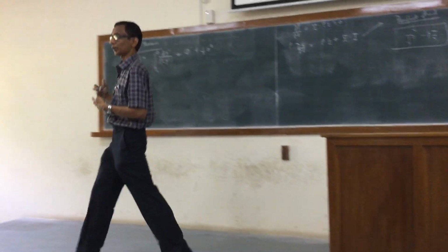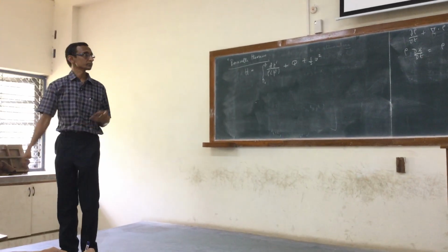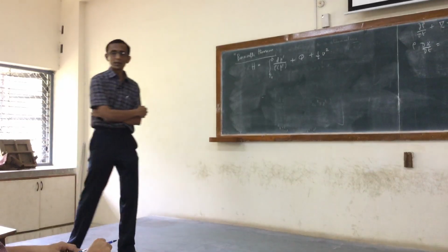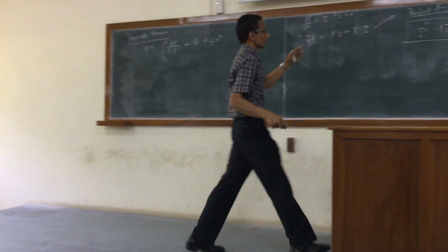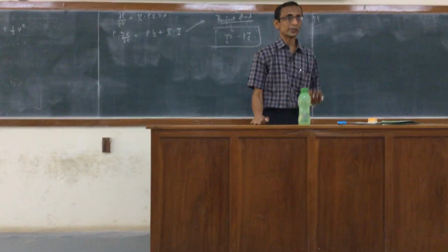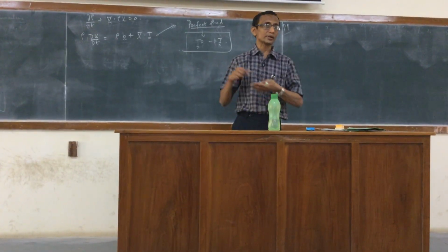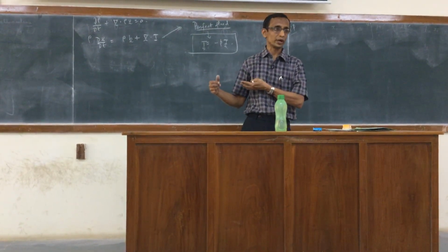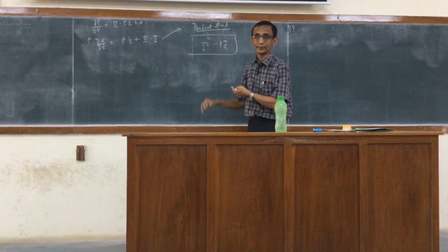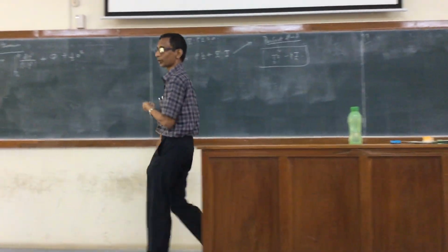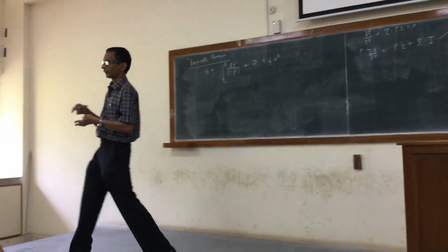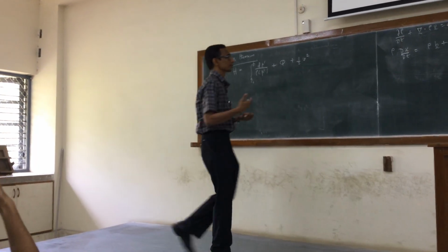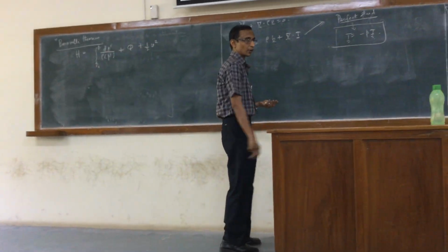No normal component coming from the deformation tensor. So often a perfect fluid is referred to as a fluid with zero viscosity, because when I put the viscosity as zero in the linearly viscous fluid, I will get this. That's one way of looking at it. A perfect fluid really doesn't have to be connected with the viscous fluid.